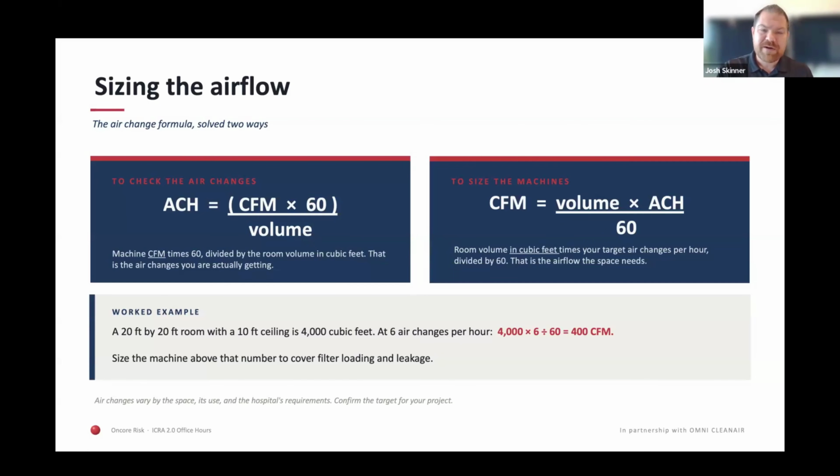And then to your point, using multiple machines versus one larger machine, I think that's something where contractors struggle. They don't understand what airflow or what CFM a machine can do. When they go get a machine that's 2000 CFM, they don't understand that that's peak and that's not standard CFM on that machine. That's not what it's actually producing. And so they'll start a containment and realize they're not actually hitting the negative pressure that they need. And it's because they're actually underpowered on machines.